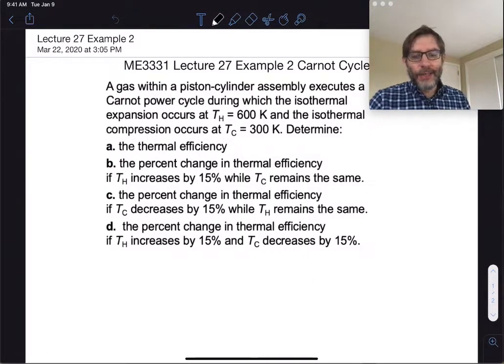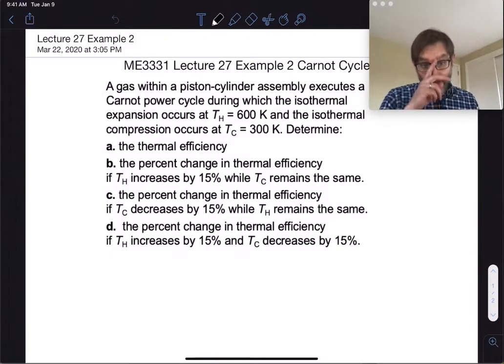It actually has processes in it that you can imagine would be reversible and ideal, adiabatic and reversible. So when I say ideal reversible power cycle and Carnot cycle, by the second law, they have to have the same maximum thermal efficiency. That's 1 minus TC over TH, okay?